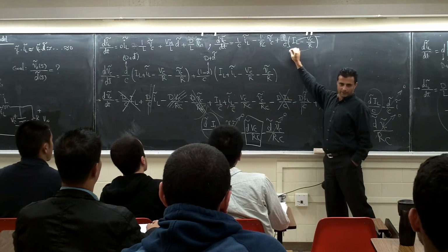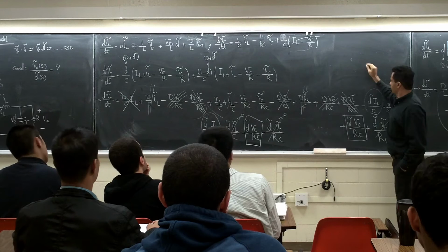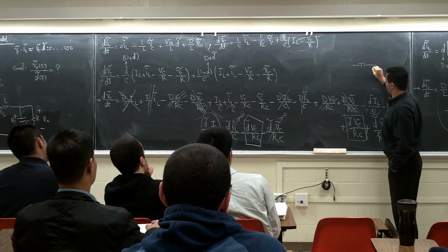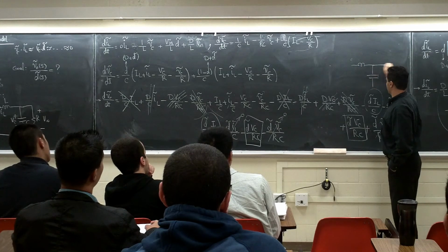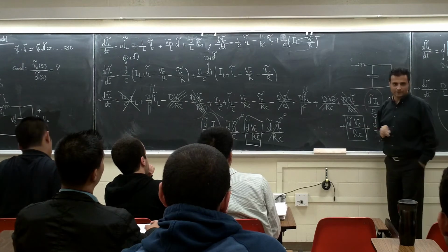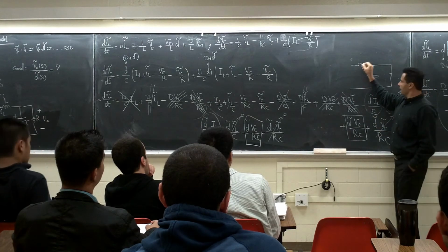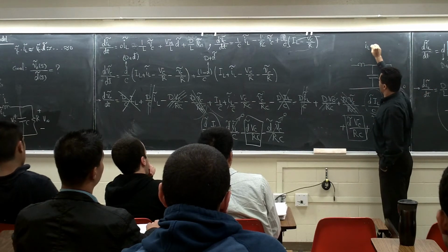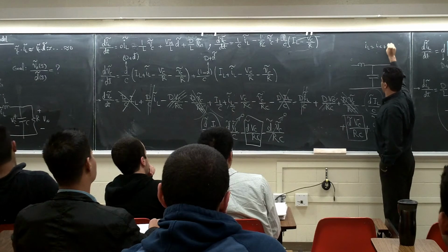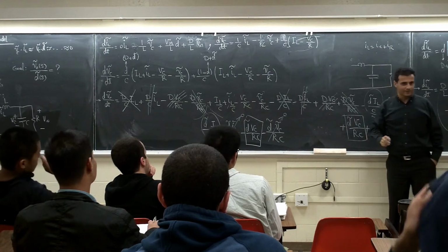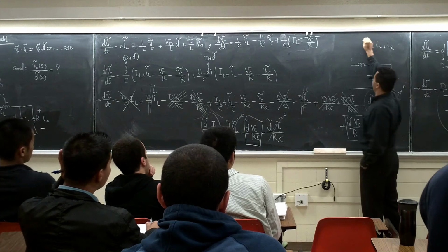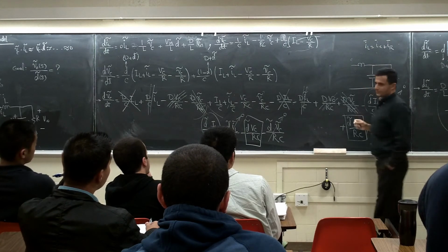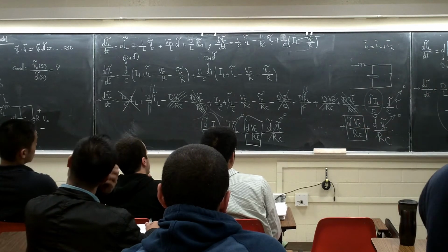Let's look at what? These are DC values, right? If we have a L here, the circuit is like this. We have a C and we have a R, right? We said IL is equal to IC plus IR, right? So IL average is equal to IC average plus IR average.